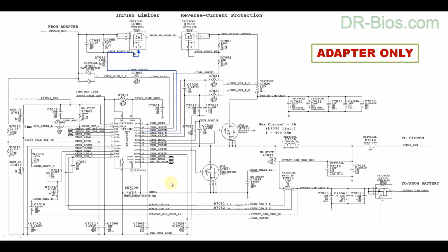In the next step, charging IC starts to drive input FETs of adapter. When it receives command from SMC, first, it drives the first MOSFET by getting its gate pin low. And as you see, the input voltage passes through source to drain of this first MOSFET, and it arrives at back of drain pin of the second MOSFET.